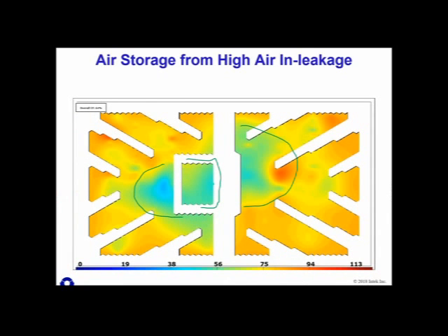So here is that bundle. It's actually got quite a bit of scaling in this bundle. The cleanliness factor only goes up to about 80-some%. But you can see here, low air in-leakage, we have an airbound zone outside the air cooler here, that bubble right there, and we have one over here as well. And then as we animate the slide, we're going to increase the air in-leakage.